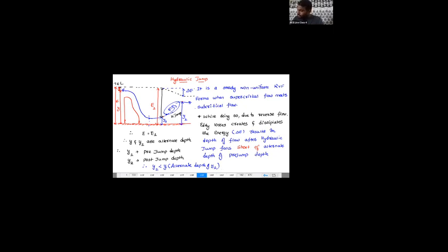So now, what is eddy loss? Eddy loss means that due to the reverse of flow motion, the energy of the water is dissipated. The water is moving and again it is hitting back. So especially you can see this in the case of corners also, eddy losses would be there. So this is one form of the loss, my dear. This is not a frictional loss. The eddy loss is different.